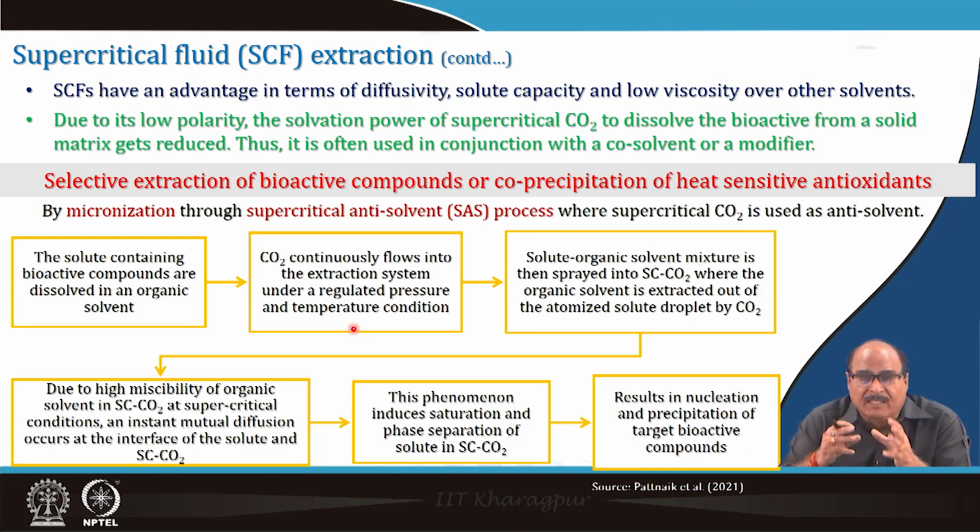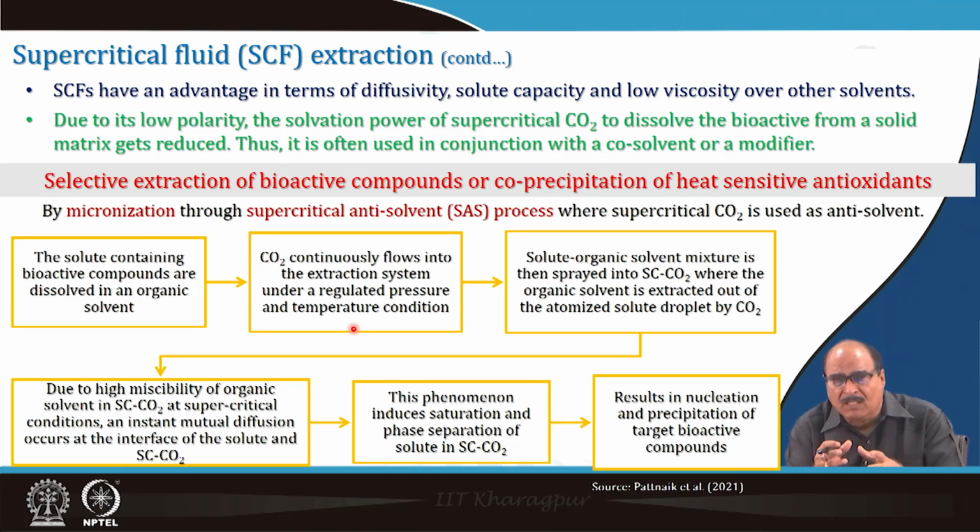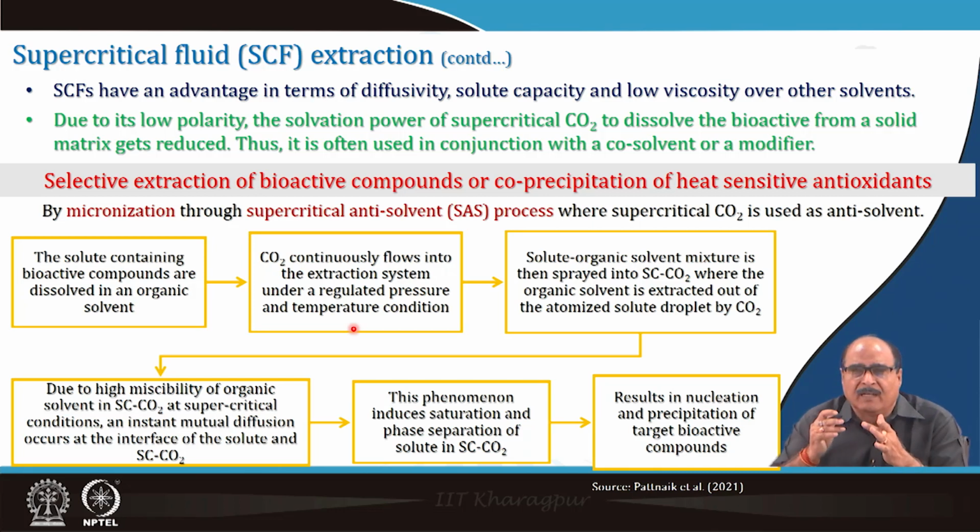This results from the high miscibility of the organic solvent in supercritical carbon dioxide at its supercritical conditions, and instant mutual diffusion occurs at the interface of the solute and the supercritical CO2. This phenomenon induces supersaturation and phase separation of the solute in the supercritical carbon dioxide, and this finally results in the nucleation and precipitation of the target bioactive compounds.